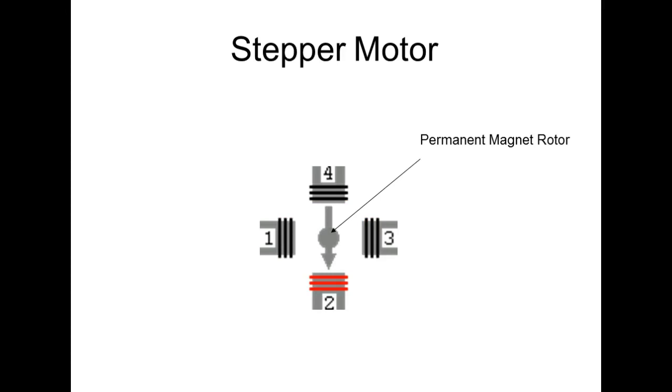So you can see what they do is they rotate the field around there, but they rotate the steps. And it moves to that step. And then we come over here and move it again. If I change the order of the rotation, the motor goes the other way. And this would be 360 divided by 4 per step.